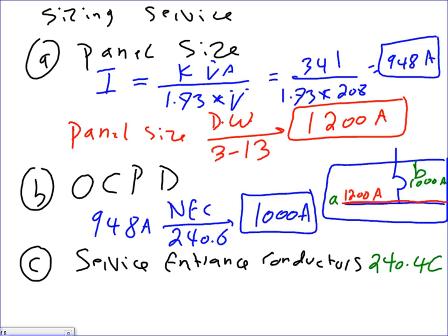Very important, guys. Where the overcurrent protection device is rated over 800 amperes, the ampacity of the conductor it protects shall be equal to or greater than the rating of the overcurrent protection device. Everybody see that? Please highlight that one. If the overcurrent protection device is over 800, which we are, then the ampacity has to match the overcurrent protection device or be higher. If we were less, then you go to B, which is you can size one overcurrent protection device higher than the ampacity of the conductor.